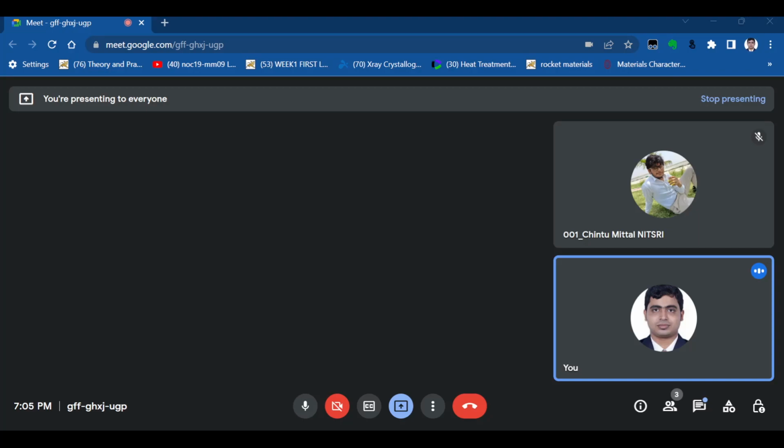Same composition of liquid, but the weight fraction of liquid are different, this is fine. Same weight fraction of liquid, this is not correct. Different compositions and weight percent, composition is not different, same composition. So this one is the right answer, B. Same composition of the liquid, but the weight fraction of liquids are different.